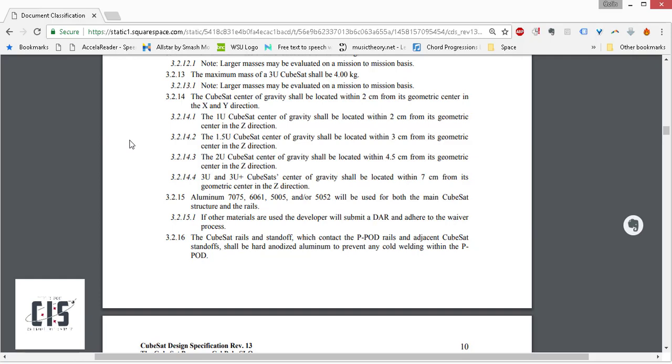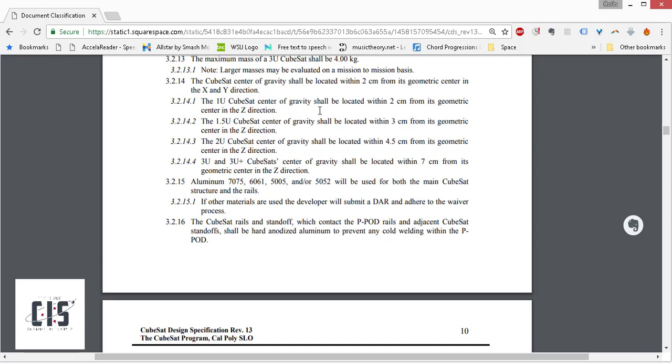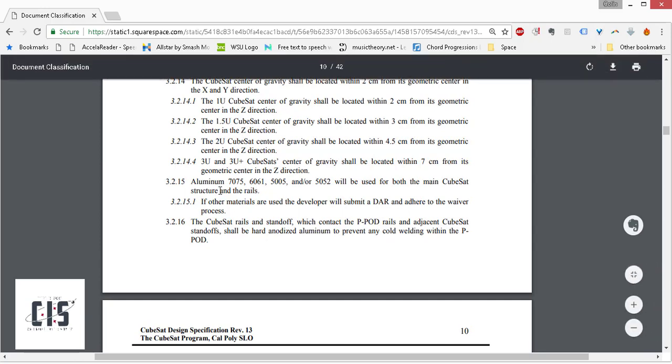At least for the center of mass, you can measure the weight perfectly fine, but how do you determine the center of mass? Not easily manually. I think just calculation is the way we're going to go. If you really wanted to, you can very carefully suspend it and draw a line down it. That line has to go through the center of mass, basically. And then you do that from another point, and then you can just roughly approximate. It's not great, so we're going to want to rely on SolidWorks, and if you really want to, you can verify that.